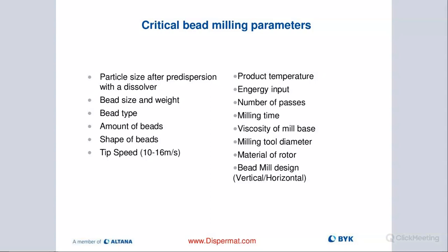Milling time, obviously, there's really no rule there. We have seen going from 3-roll mills to a basket mill from 18 hours to 45 minutes. But we have also seen some instances where we use a basket mill in some specific application, they milled for 2-3 hours. But really extensive, long milling times overnight, we don't really see it. But depending on your formula, some mill quicker, some take longer. Again, we talked about that earlier. Viscosity is critical. Try to stay within 2 to 8,000. That's usually a sweet spot.